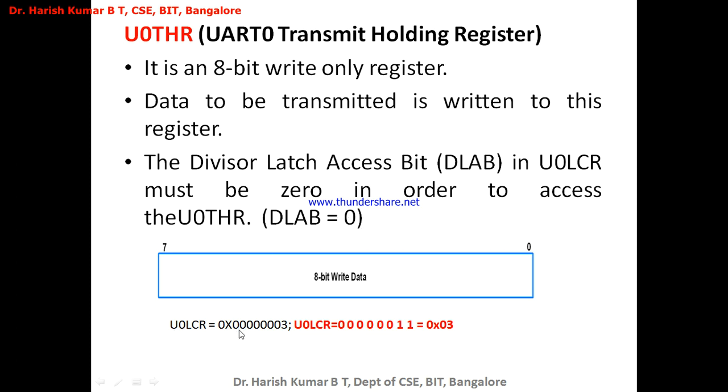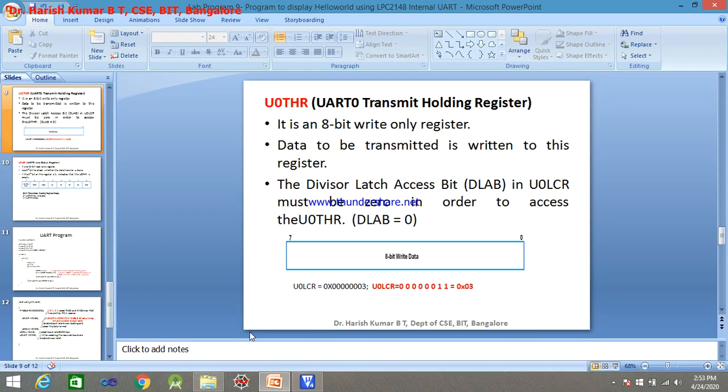After resetting back, the value is 0x03. U0LCR is assigned this value. It's an 8-bit register, so many zeros are not required.